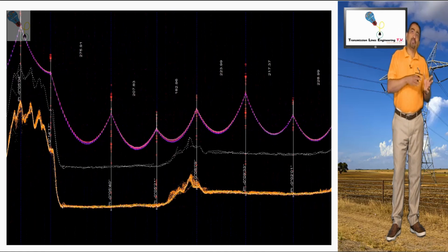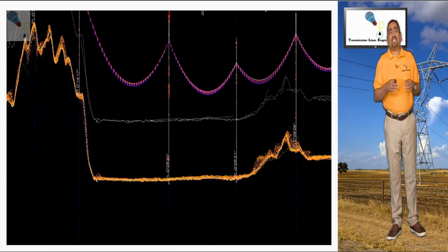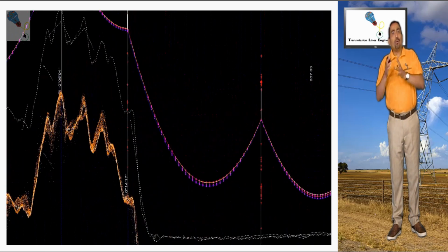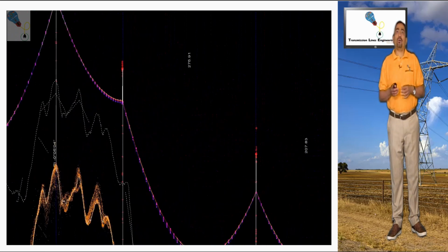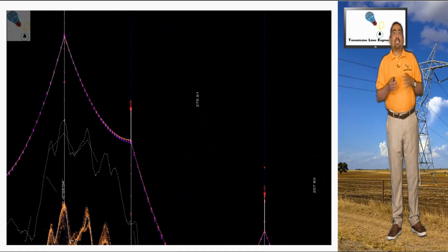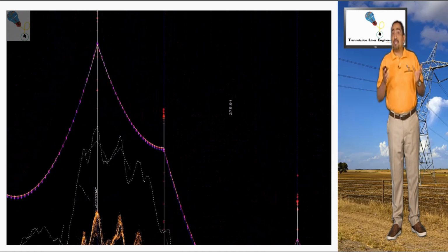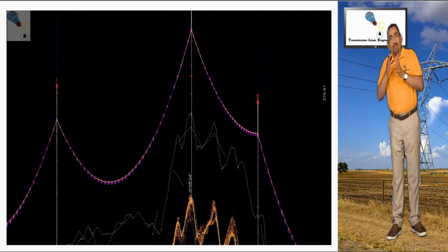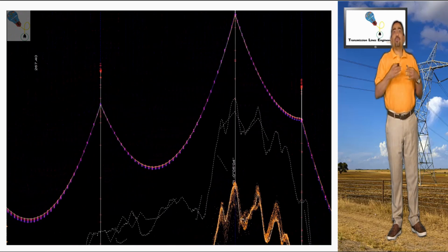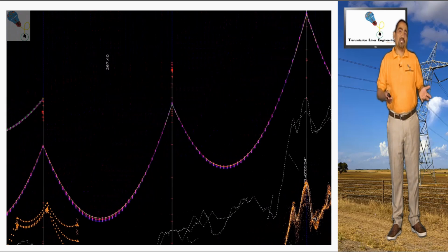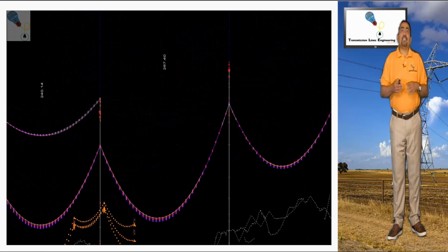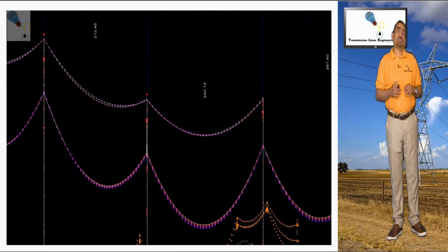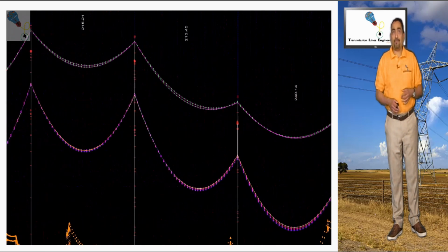The existing cables can be modeled to match the points registered by the LiDAR, and by knowing the type of cable installed and the temperature, it is possible to calculate the mechanical tension of that particular cable at the recorded temperature to model the cable under different loading conditions. And in this way, we can get an idea of the tensions on the existing structures.